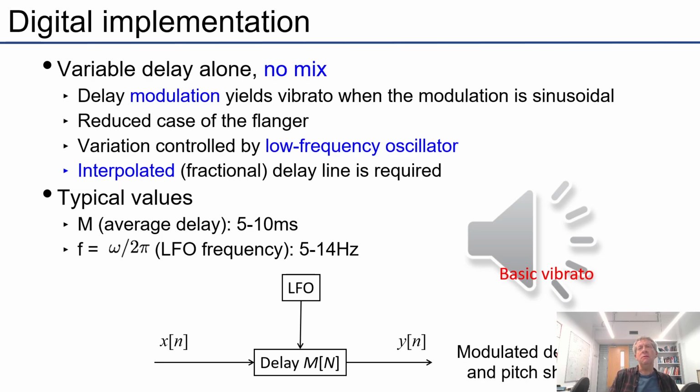And the frequency of this modulation is controlled by a low frequency oscillator. Also, we need a fractional delay because here we're continually varying the delay. So what happens if the delay is, say, more than 5 samples but less than 6 samples? So, why don't we talk about these two new concepts we're introducing here? Let's first talk about the low frequency oscillator because it didn't occur in basic delay and didn't occur when we were discussing MIDI or a noise source.